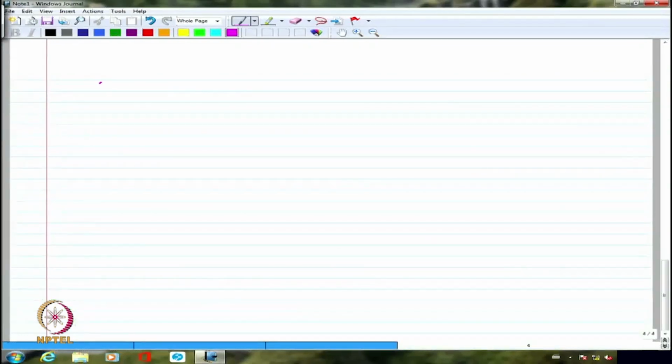So I have to say 230 minus whatever is the current, that was 100 ampere I suppose, and how much was the armature resistance? 0.5? 0.05. So this is going to be my EB normally, right? Where did I keep the paper? Okay. So this is what is my EB. How much is it? I have calculated it, but I do not have it right now.